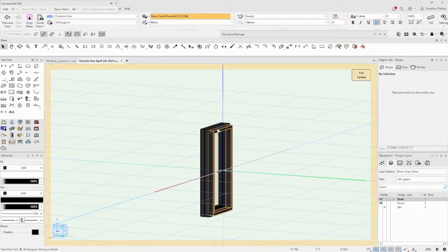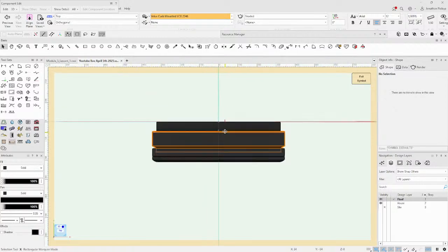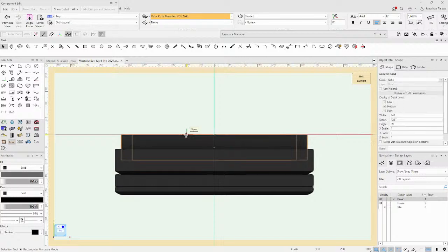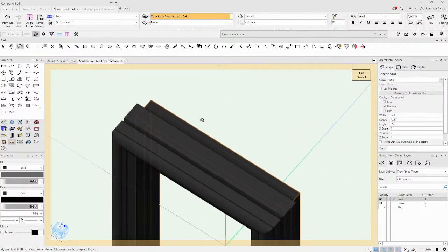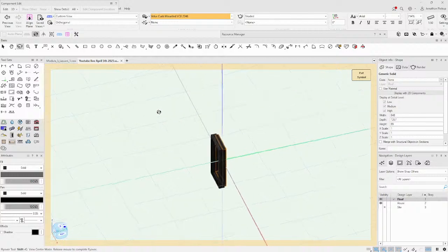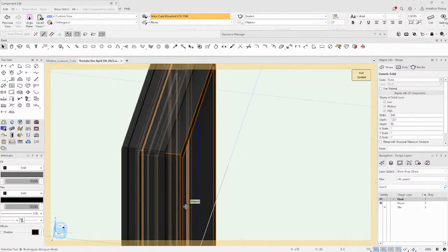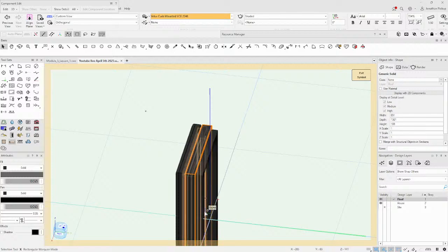And if we look at this in a top view, there it is there. So in top view, what you need is you need to create your extruded objects on this plane, and then they come down. And that's just the way it is with the Vectorworks Skylight. It uses this face here as the insertion point of your roof. Then that is the part that should be fitting onto the roof. There should be a flashing in here somewhere, I think.